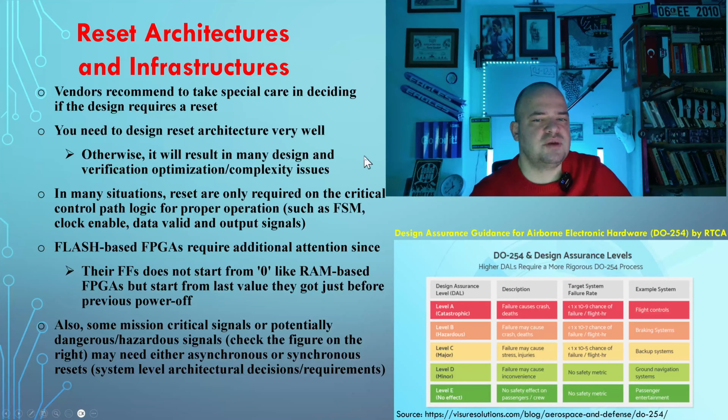So you are not supposed to reset, let's say, huge standard logic vectors going out from your entity as well. But you need to provide some good comments saying that I didn't provide a reset value for this signal since blah blah blah. So you need to explain that.